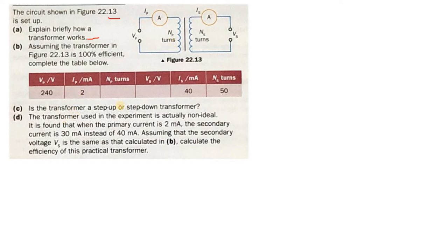So you can write this part first, that it depends on electromagnetic induction, where, it's difficult to write, so I'll just say what happened: the alternating current in the primary coil induces a varying magnetic field in the soft iron core, which creates an alternating induced EMF in the secondary coil, which generates induced current. So we can see the current in the secondary coil now.